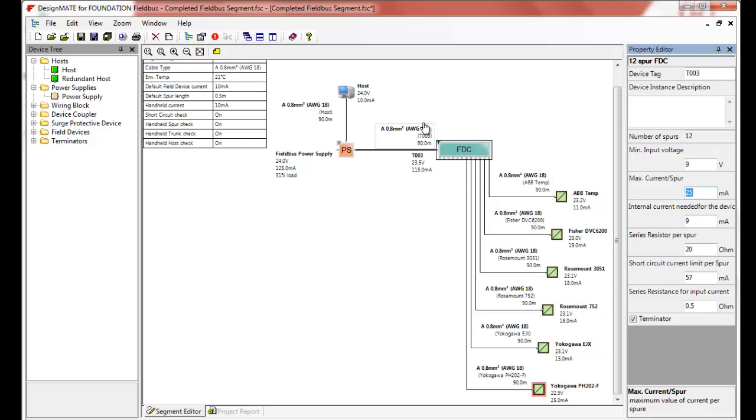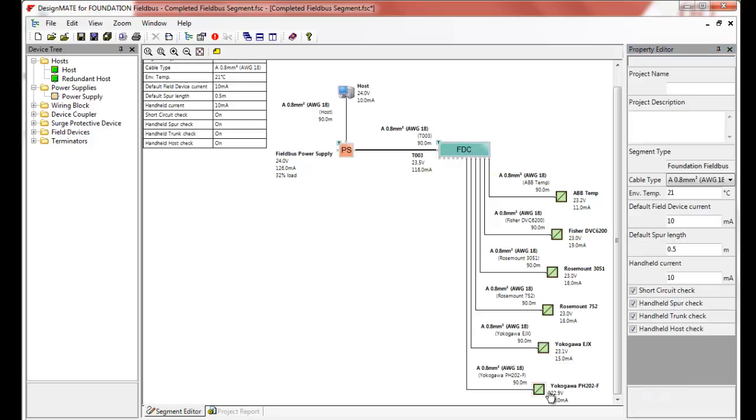In this scenario though, what you can actually do if you're uncertain is go back to your particular product specifications for that product and double check it. In this case, with this device, let's say I go back to the web or I dig through the pamphlet that comes with it, and I notice that, man, I don't know what happened there, but it shouldn't have been 25 milliamps. It should have been 41 milliamps was the maximum draw, right? So let's adjust that, and look, red box goes away.